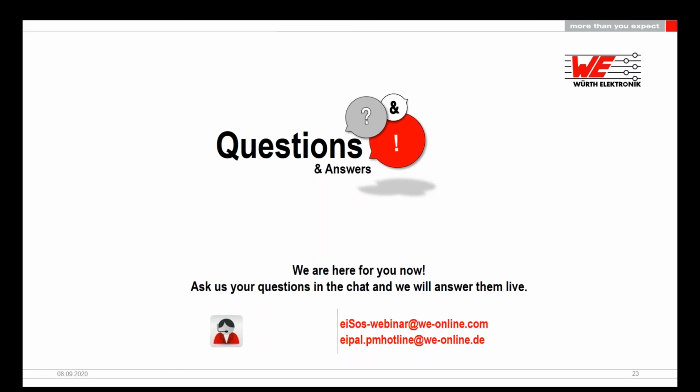First question, can the side view LED be used as top mount or reverse mount? Yes, by hand, the side view LED can be used as top mount or reverse mount, but not by pick and place machine. And it's also not recommended to use the side view LED as top mount or reverse mount, because the contact surface is limited and the distance between the contact pads is too small. So after the soldering, it may cause a short.